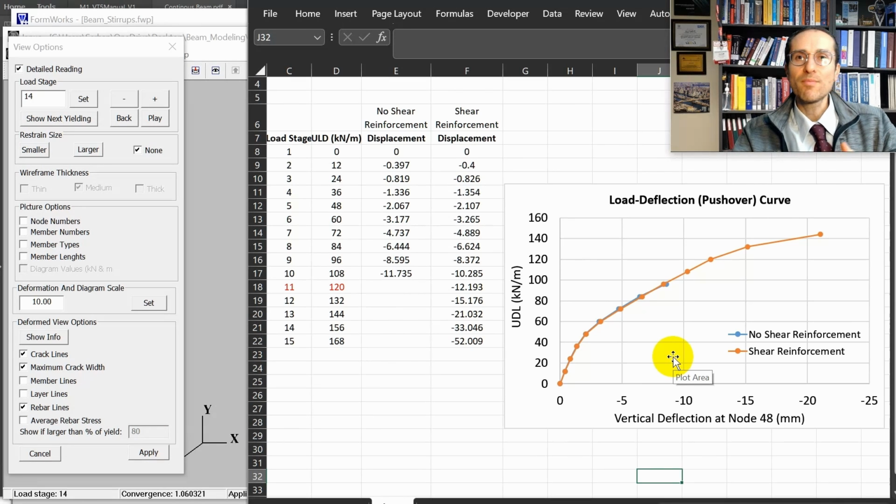This could be for a performance-based design, or this could be for an existing structure, because in existing structures, it's really difficult to pass. If you do the inelastic analysis, nonlinear will give you an idea. Is it failing in shear? Is it failing in flexure? What's going on? What are the loads? What are the crack widths? And you can make an appropriate decision depending on the results.